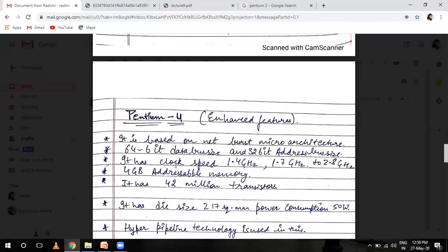Pentium 4 is faster than Pentium 3, and it is based on NetBurst microarchitecture. Its features include a 32-bit microprocessor, hyper pipeline technology, a rapid execution engine, and a 100 MHz system bus that delivers 3 times the bandwidth of the Pentium 3 processor, and it is designed to enhance online gaming, digital video and photography, speech recognition, and MP3 recording.